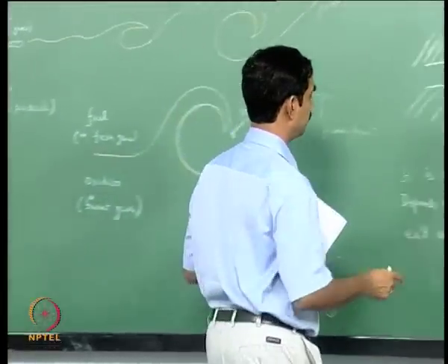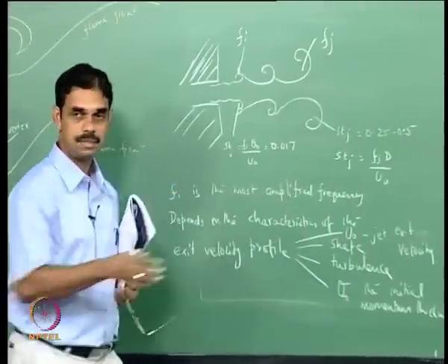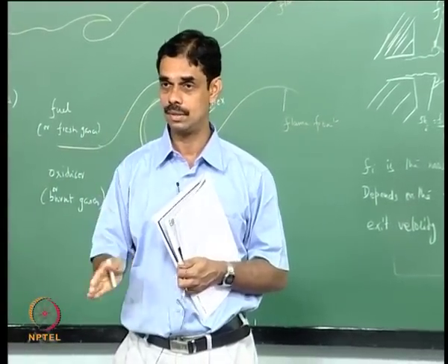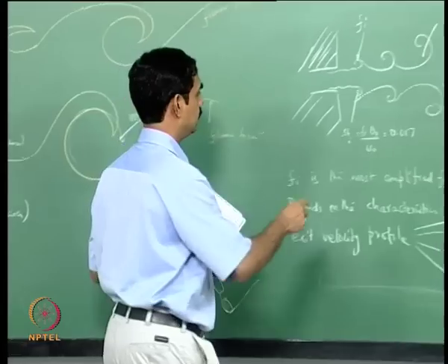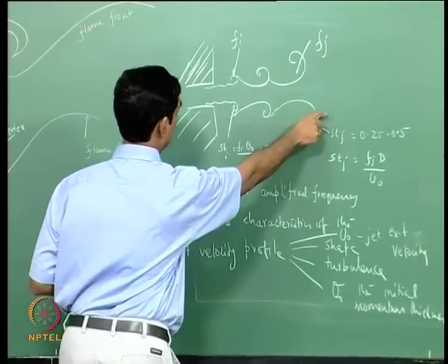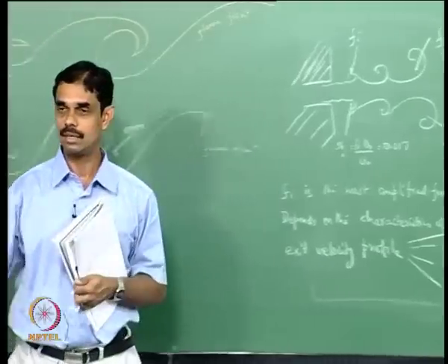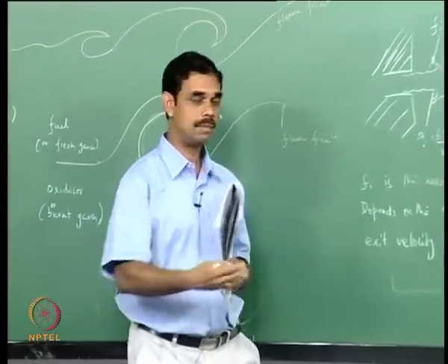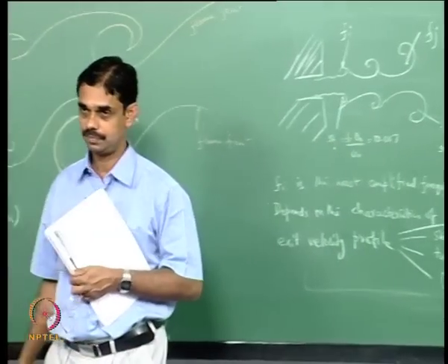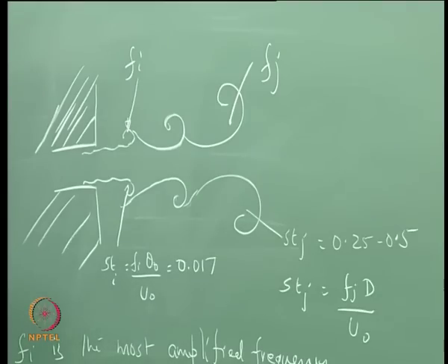The two Strouhal numbers, and if you see a spectrum of a jet, the noise, it will have many frequencies, it is not just one particular thing. So you will have a frequency associated with the initial layer and a frequency at the other layer, and you will see a kind of broadband spectrum, but with some preferred frequency. You will still see a prominent peak there. So you will see a lot of frequencies, but some frequencies will be preferred.